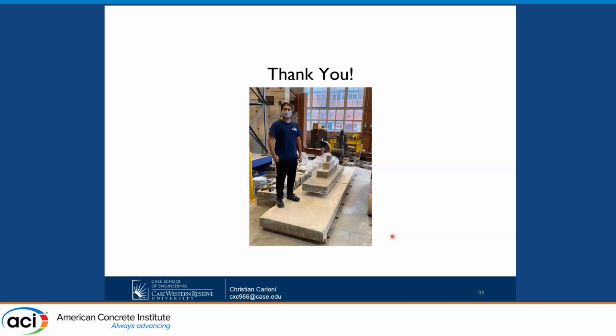Thank you. Yeah, very interesting question and very appropriate. So what I can tell you is this. I'm going to start with the second one. There are tests. It has been shown that there is size effect for UHPC. The question is, if your crack is opening, the fibers will stop or delay the opening, but the initial cracking is concrete, because to crack the fibers, they need to open, so the initial crack is concrete. So that's why there is still size effect. And actually you will have even more. If you look at the data, they will be even farther down that curve because your aggregate size is very small.